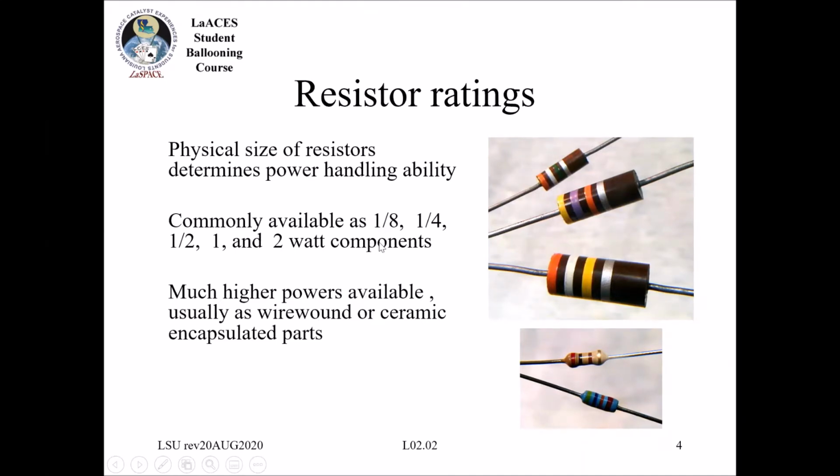It's really important. And just down here, looking at these two, I can tell you that if you see a blue resistor like this, normally I think that's a 5 or 1% tolerance. And then the beige ones typically are the higher tolerances, as well as you can see that there's an extra band on the blue one for the precision that I was talking about.